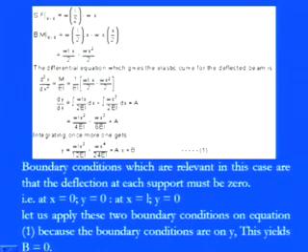So now we have, since only the variation is x, the integration of these things x into dx. So dy by dx is nothing but equal to WLx² divided by 4EI minus Wx³ by 6EI plus A. So now you see here we have a slope equation, and in the slope equation we have one constant term, that is A.